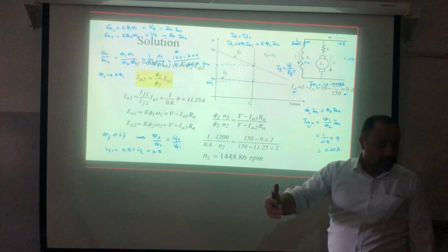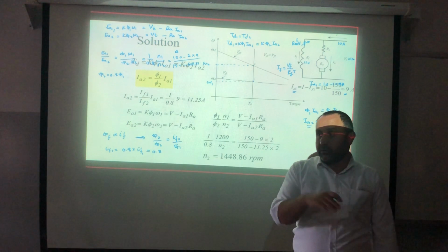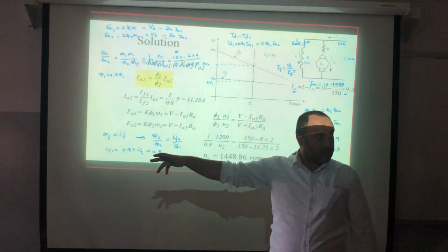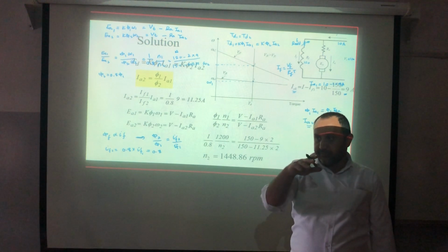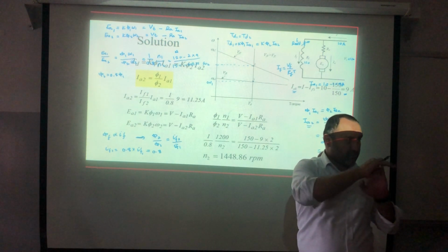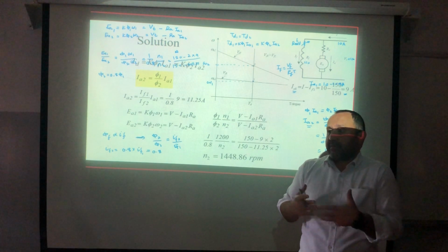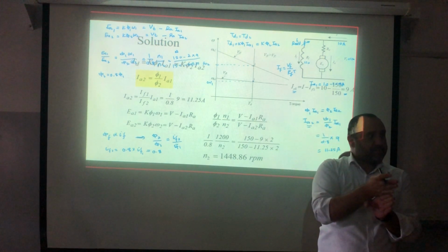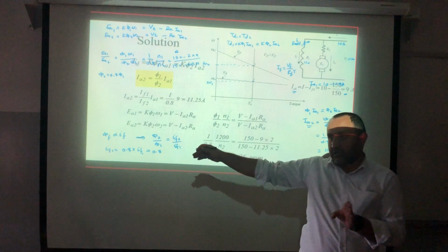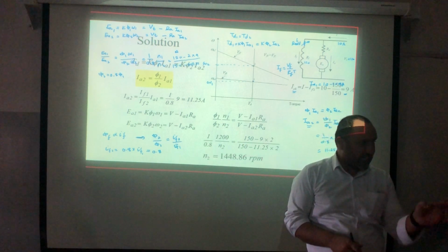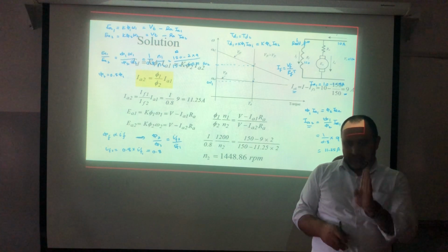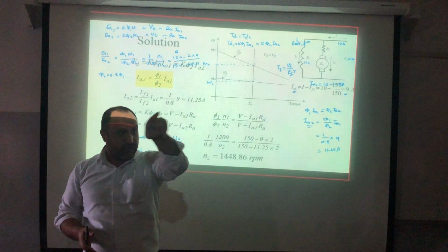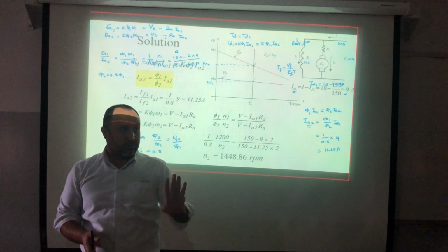Later on, I will plot what we call the constant torque region and the constant power region. In the constant torque region, I will assume that the torque is constant, which means that I can provide the maximum capability in terms of the torque at certain speed. After that, I should enter what we call the flux weakening. The flux weakening is from the base speed until the maximum speed, and all of that curve is valid for the continuous mode of operation.